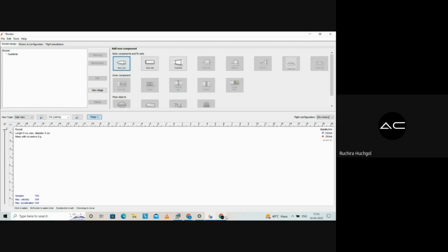The ideal condition for stability of the rocket is that the center of pressure should be behind the center of gravity. Now, the formula to calculate the static margin, which gives you the distance between the center of pressure and center of gravity, is 2 times the diameter of the body tube. Now ideally you don't actually use this 2 times the diameter of the body tube. The range for stability of a model rocket is calibrated around 1.88 to 2, and it's considered to be more than efficient for model rocketry.